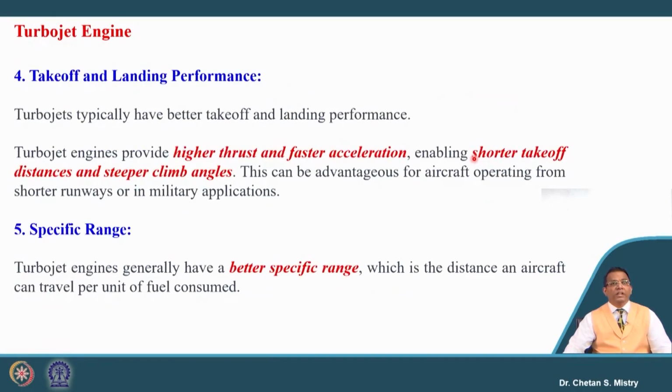Then the next attraction is the takeoff and landing performance. It is having better takeoff and landing, and this is because of higher thrust and faster acceleration. So we can have a short takeoff distance and a steeper climb, and this is a requirement for military purposes. Later on, people realized this also has a benefit in terms of better specific range.